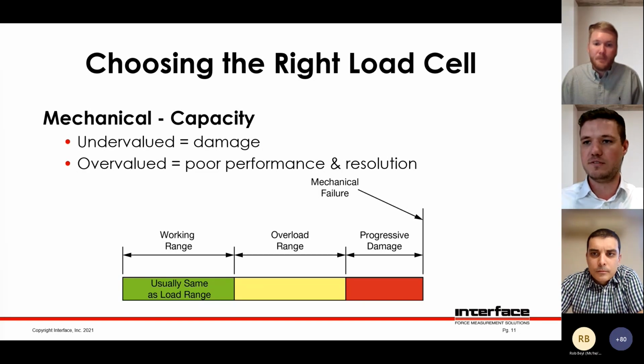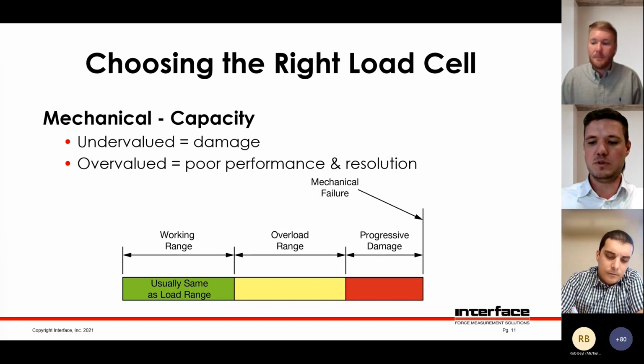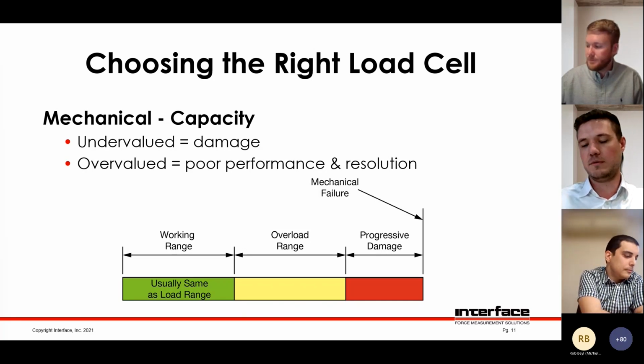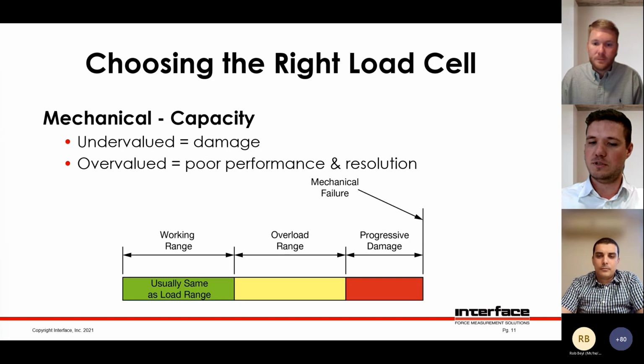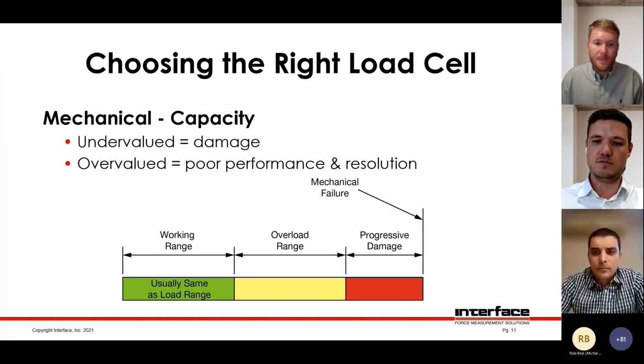The load cell needs to be able to survive these unforeseen events. So the working range, we try not to go over that working range at all. But you do have 50% headroom, which definitely helps. And some customers do use that 50% headroom as part of their measuring range. There's several disadvantages to doing that.